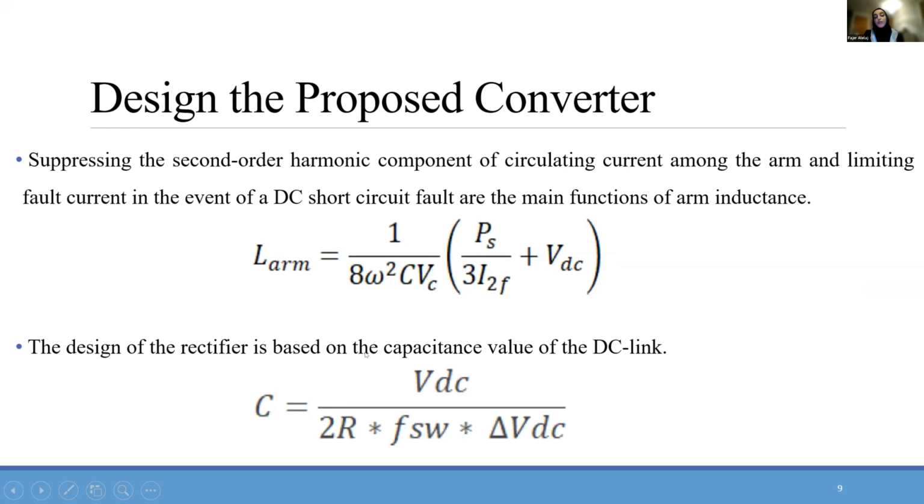The design of the rectifier is based on the capacitor value of the DC link. As you see here, these are the equations to determine the value of the capacitor. It will depend also on the ripple of the voltage, the voltage of the DC, the switching frequency, and also the load resistor.